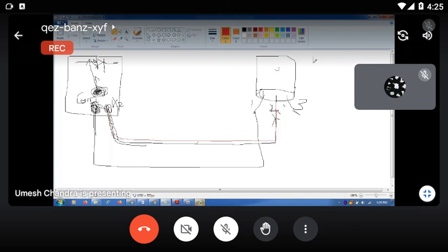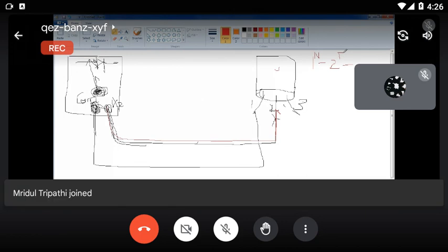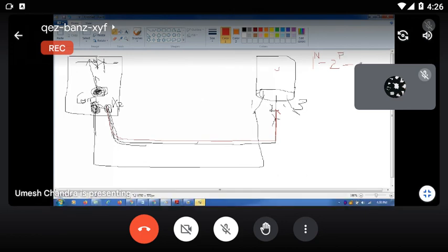That means just write here 1, 2. 1 is negative, the black lead connected with the first terminal, that is N. And the second terminal, where you connect the red probe, is P. Suppose you got some voltage, say 0.613 volt, for example.